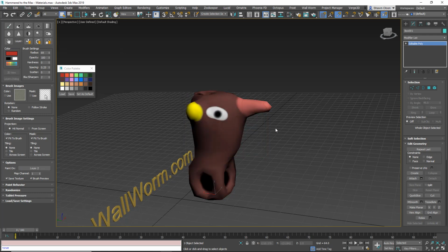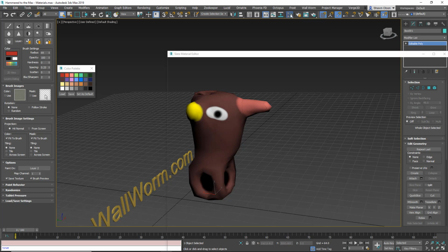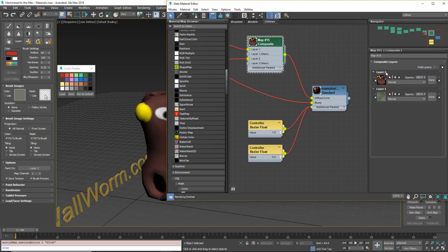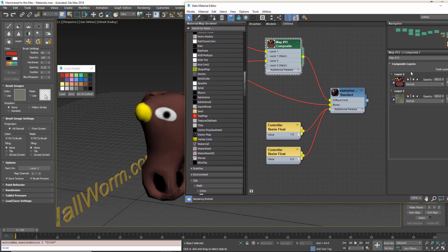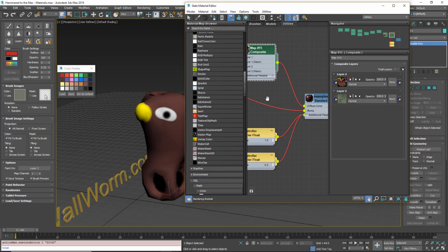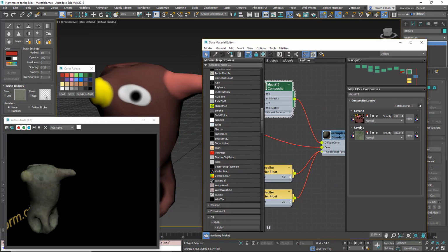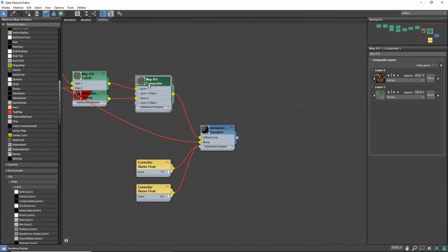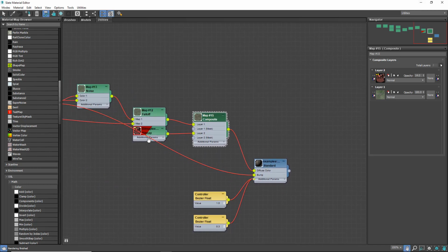And now we're going to go into our material editor. We're actually going to put this below. Actually, we'll keep this on top, but we're going to assume that this is really faded. We're going to change this to the opacity of very low. Our viewport isn't updating very well here. So we're going to just assume that it had these old paint levels that were pretty much mostly faded off. We'll do it like that. So now we have this procedural texture and a mixture of the procedural plus this bitmap that we painted on here. Now we need to bake that all together into one flattened bitmap.